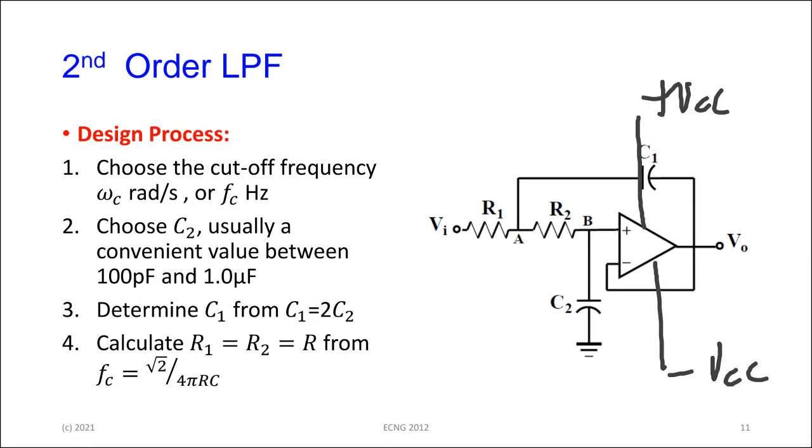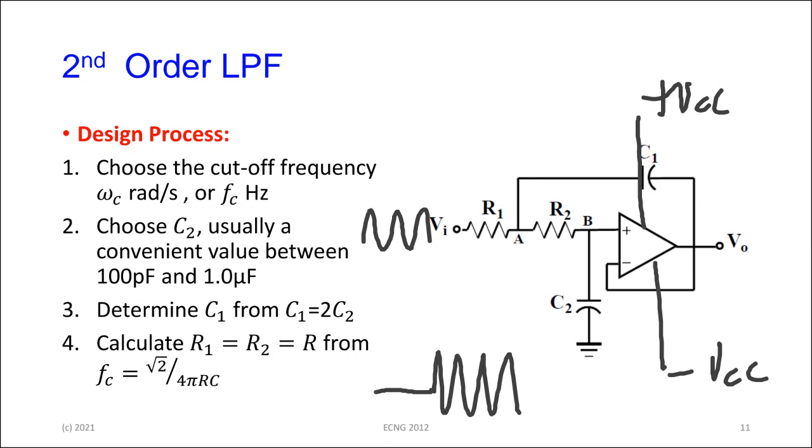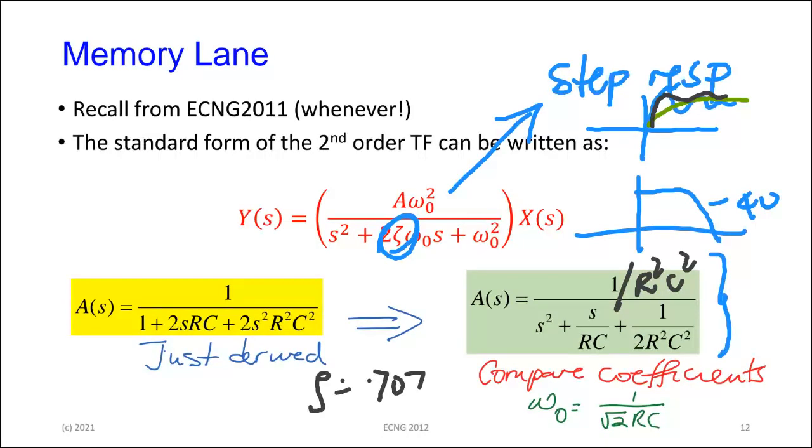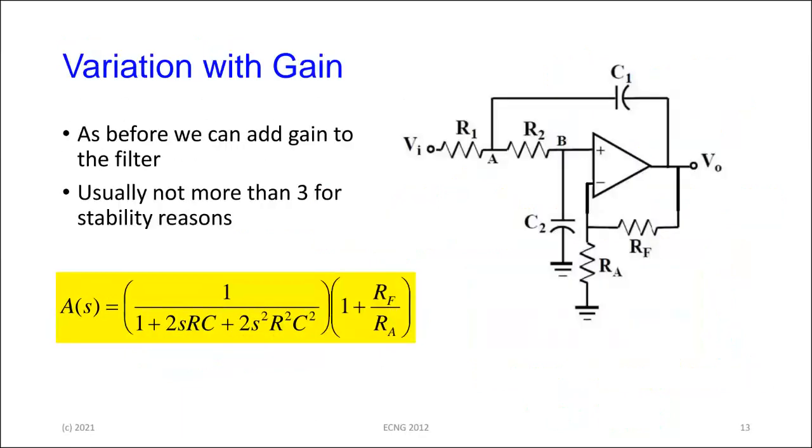At some point in time, you're going to switch on the op amp. Once you switch on the op amp, if you have anything appearing here, just for argument's sake, you're going to see a step change in the input, from when the power is off and the op amp is seeing nothing, to when you turn on the power and V in sees that. You're going to have a step change on the input.